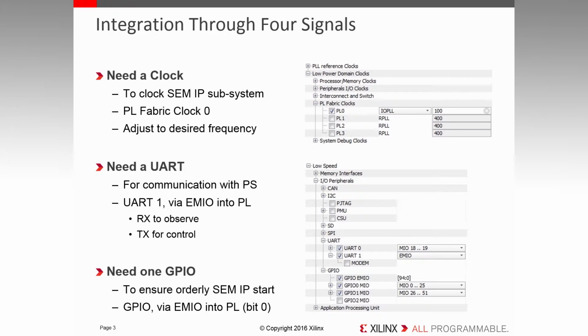However, if the design loaded into the programmable logic needs to use the ICAP, the programmable logic design needs to wait until ICAP has access to the configuration RAM. This is the case with the UltraScale architecture SEM IP.